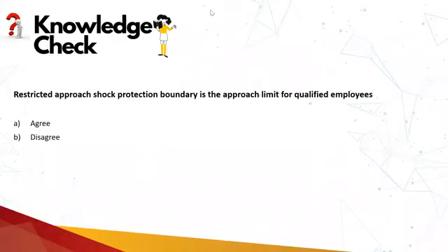Yeah, this boundary is for the restricted approach shock protection boundary, the approach limit for the qualified employee. This is the right option.